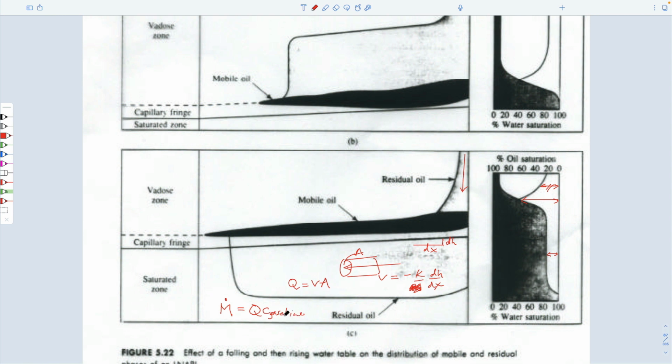Concentration that's dissolved in water. So it might be 1,000 parts per million, typically at very low concentrations. But immediately it allows you to calculate the rate at which the dissolved, certainly you can calculate the rate of flow just given by the inclination of the water table. And you can also calculate the rate at which fluids dissolved in water and carried with the water are transported horizontally along with it. And so there'd be different transport mechanisms in the air.